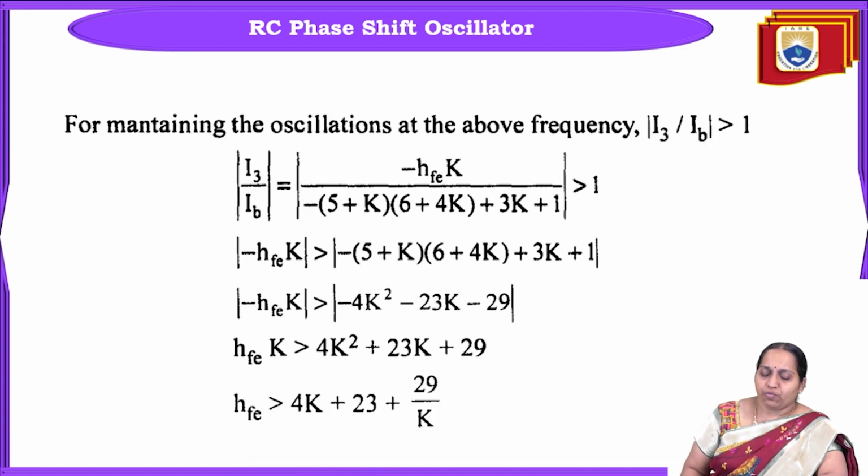We'll just see what the condition is, or what the minimum value of HFE is that we need to have to get proper oscillations. So for maintaining oscillations at the above frequency, the gain should be greater than 1.